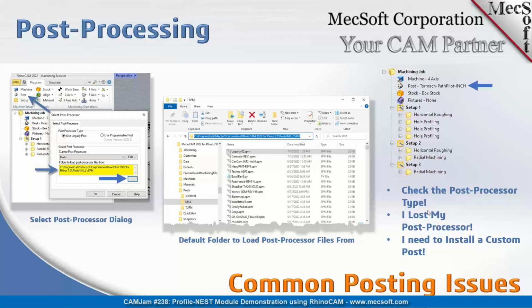So the next, third item over here on the right is, I need to install a custom post. This is the same procedure as verifying that you are pointing in the right direction where your post is. If we've supplied you with a customized post processor, it would typically be one of these posts in this list, maybe with a rev number on it. Like for this one here, we have Haas PMT-Rev1. That is a custom post that we supplied to a user that was common enough for us to add into our standard post list.